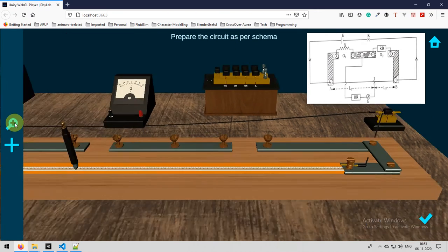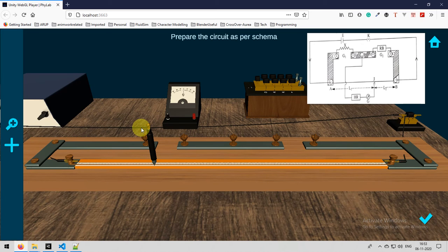So the basic diagram is done. And we need to close the bridge between the two wire gaps, G1 and G2. First I will close the gap G2, which is connected to a resistor box. I will take two wires, one to connect to the resistor box, and after that I will create an unknown wire and then connect it to the G1 gap. That will be my unknown wire.